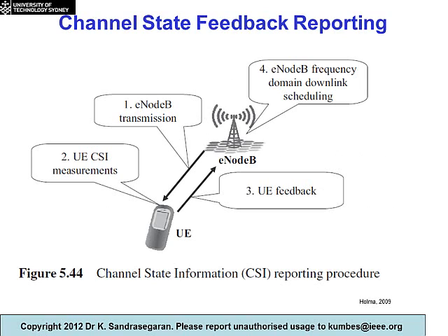Okay, so the key important thing for all of this, both packet scheduling and link adaptation, is the feedback that comes from the UE. The E node B transmits certain reference signals, and these reference signals are measured by the UE, and the UE then feeds that back to the E node B. Based on the information that it's receiving from the UE, the E node B performs both packet scheduling and link adaptation.